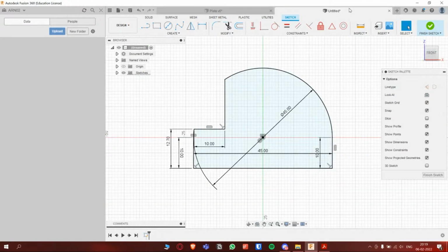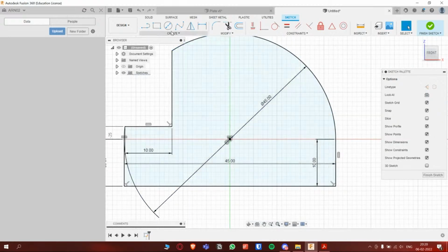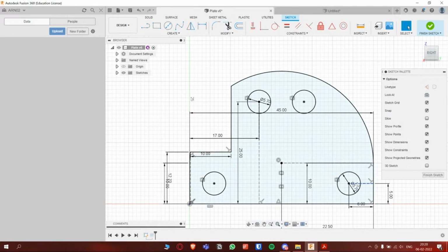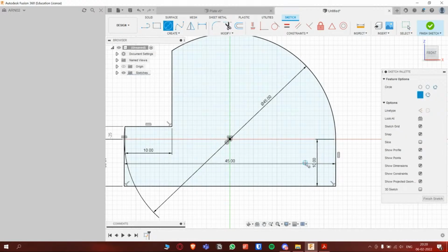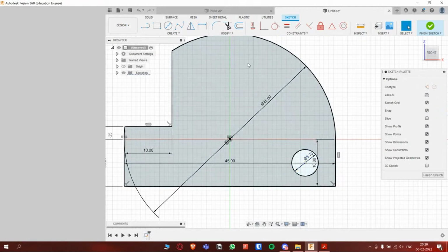We are gonna go back to this drawing that we made, and we're gonna create this circle over here. It's 5.7 millimeters in diameter, and we can see that the distance between the center of the circle and the bottom line is 5 millimeters, and the distance between the center of the circle and this line is 6 millimeters. So we're gonna go to the drawing, create a circle which is 5.7 millimeters in diameter, and we can use the dimension tool or D on your keyboard, right?